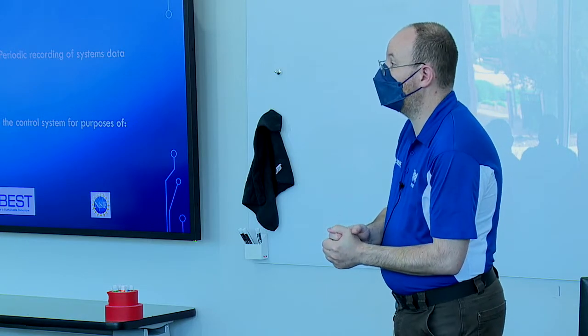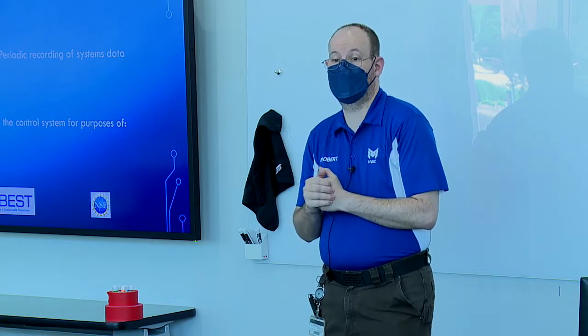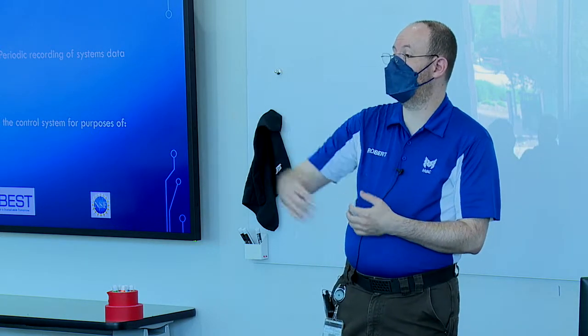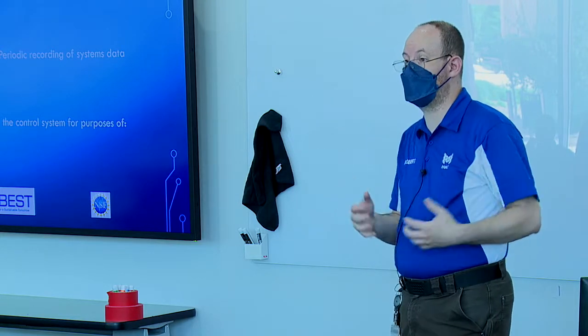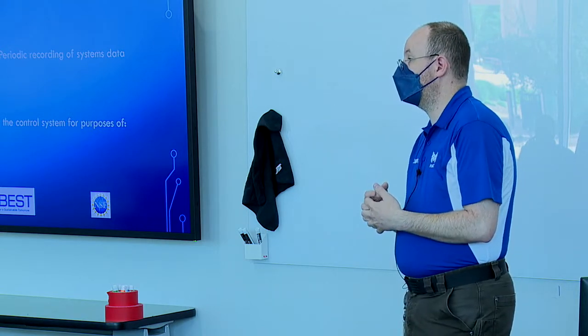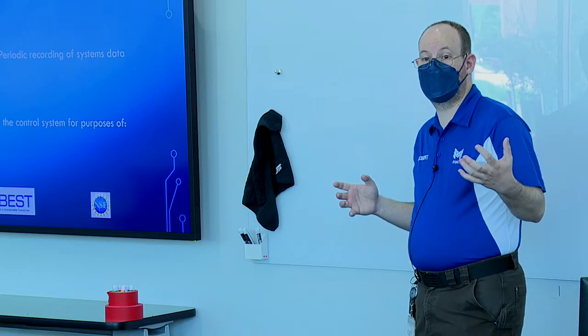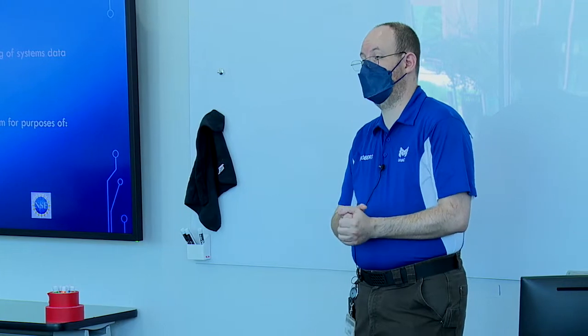They can also be really helpful for reporting purposes. Especially if you're logging things like your building's energy usage. If you've got BTU meters on your chilled water, for example, or you're monitoring your electric meters or your gas meters, all of that kind of data, it's great data to have in your system, but again, what use is collecting data if we're not going to do something with it?